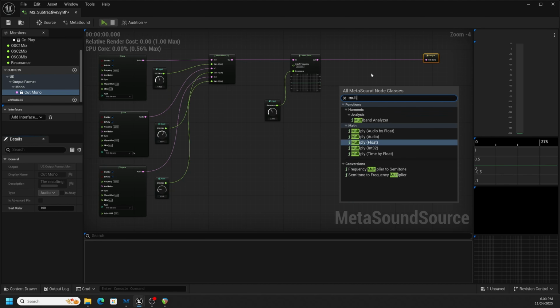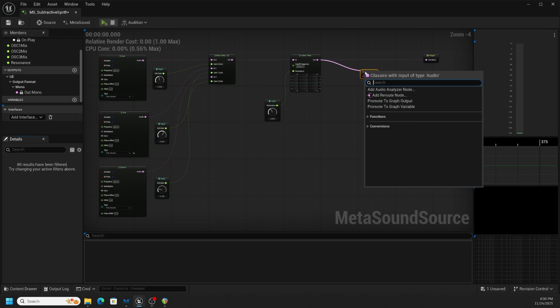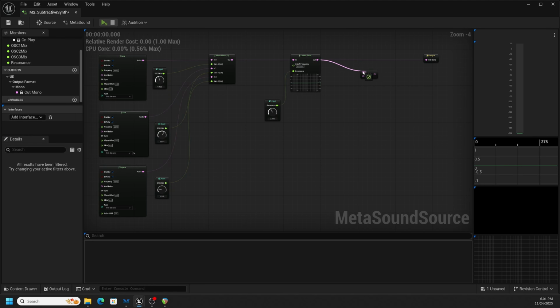We're really multiplying here. We're multiplying audio, and that seems like a strange idea, but that's what we're going to do. So the original signal is 0 to 1. That's the amplitude of the audio. Okay, and then if we multiply that times 0, we get no amplitude. If we multiply it times 1, then we're getting full amplitude. So it's really an attenuator. It's a VCA, you know, you might even call it an attenuator. It's where we're attenuating the signal rather than actually boosting it. But we'll let that go for now.